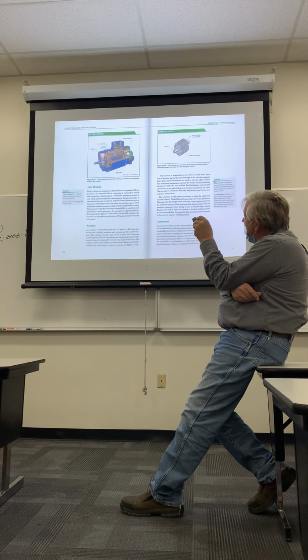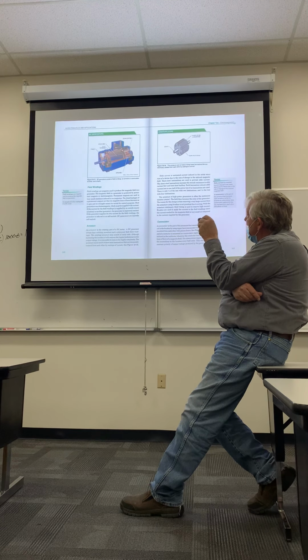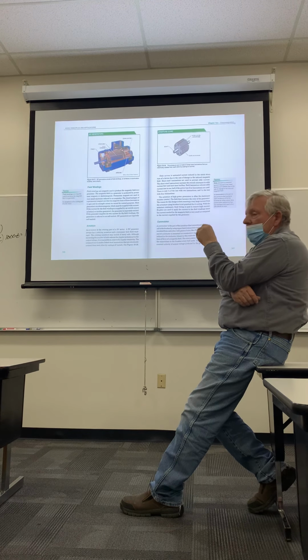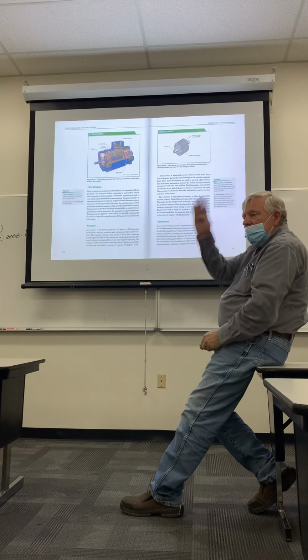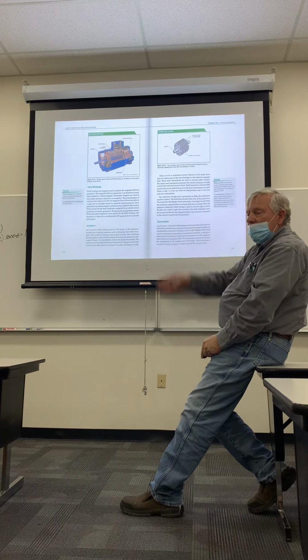armature, which is this piece here that's resting on bearings on either end, very freely turns inside of those field windings, and as that turns, it creates little bits of voltage by passing that conductor through those lines of magnetic flux.